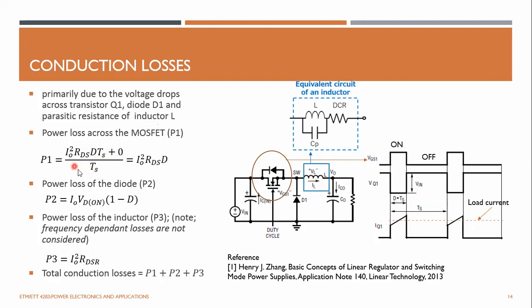And from here, the power loss is the summation of the energy of the charging phase plus the discharging phase, divided by the total time period. We know the power loss in the discharging phase is zero because there's no current flowing through this transistor. In the charging mode, the inductor current will go through this power switch. The average current of the inductor is the load current.